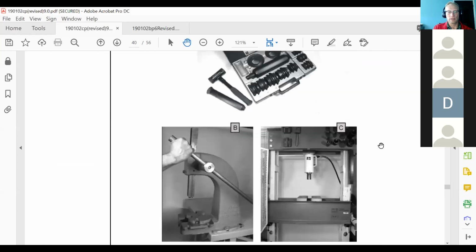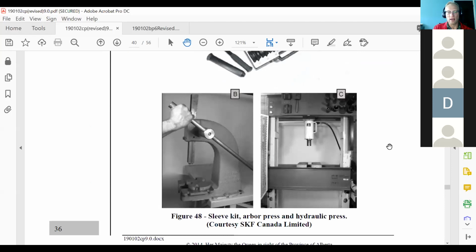The other thing you can do, and this is for wheel ends specifically, if you don't have a driver for a bearing race, use the old race. Now the problem is, you're driving a race with a race that's the exact same size. So you run the risk of jamming it in the bore. So you have your wheel hub and you want to drive the bearing into the bore here, but it's the same size as the other bearing race, right?